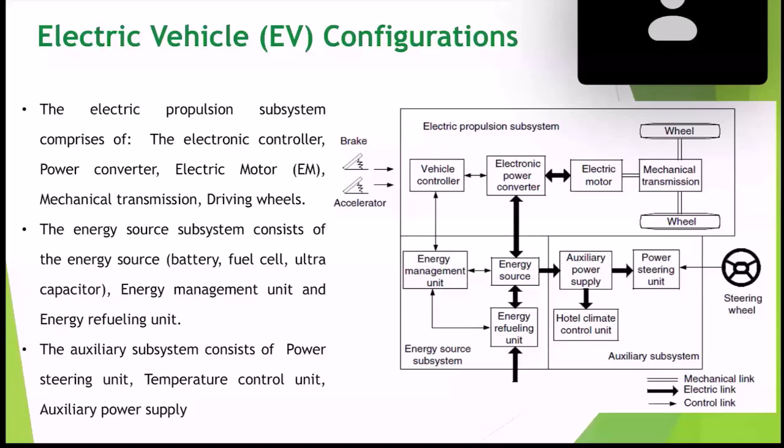So what is meant by torque-based vehicle control? It considers the torque requirement from the vehicle or from the powertrain, which may be an engine or a motor. What factors require torque from the power producing system? The driver may require steering, or any auxiliary systems like the AC system and cruise control systems. Different systems will require torque from the engine or motor, the power producing device. In order to satisfy the torque, the respective motor or engine, and in some cases both the hybrid motor and engine, have to work.